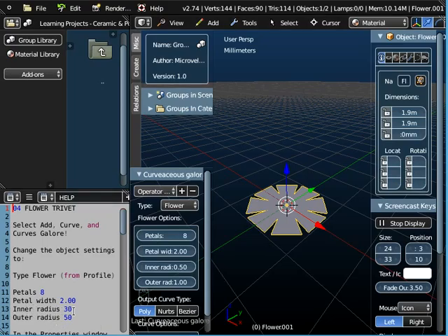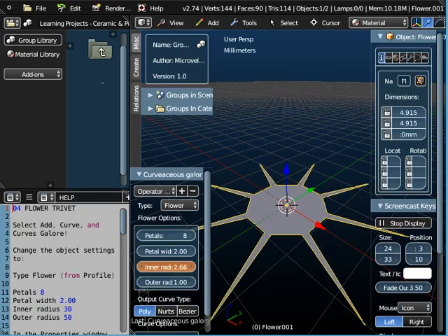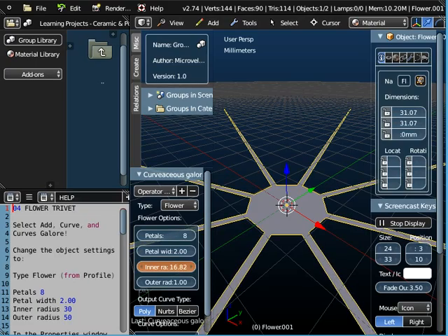We want to change the inner radius to 30. Well, if we click on here and do it, it's going to be really quite slow going up to 30. So an alternative way of doing it is if you hold down the mouse button and drag this, you can dynamically see what's happening as you change it up to 30.